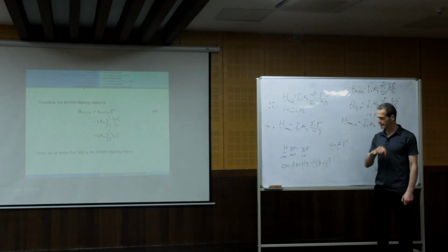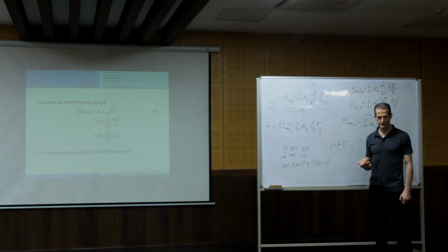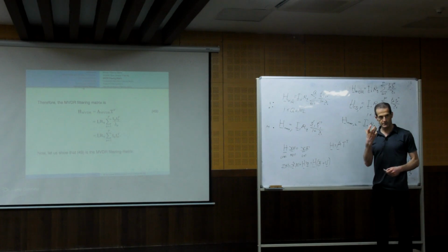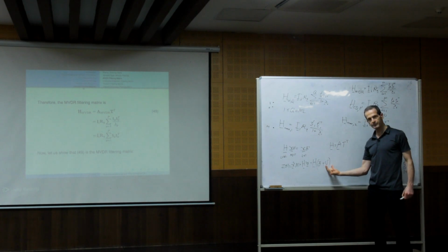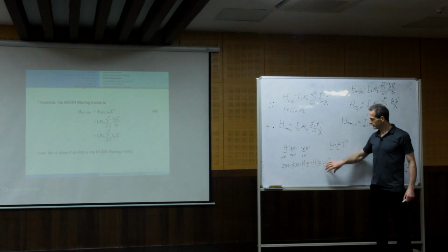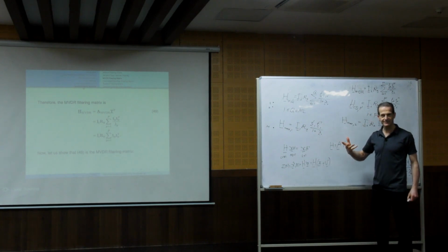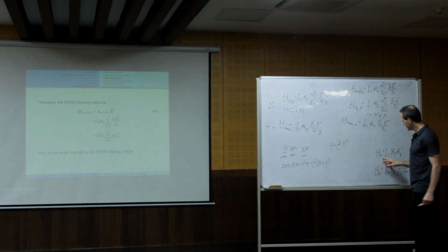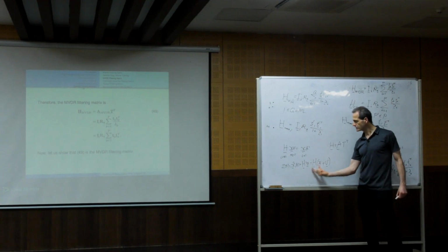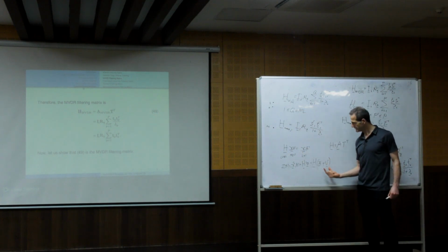So it's MSE-based maximum SNR filtering. So it means that it gives some importance or weight to both this and this, how they differ from X1. So the residual noise is also important. Here, we care only about the distortion. So we want this to be as close as possible to X1, which means that we don't give any importance to the residual noise.